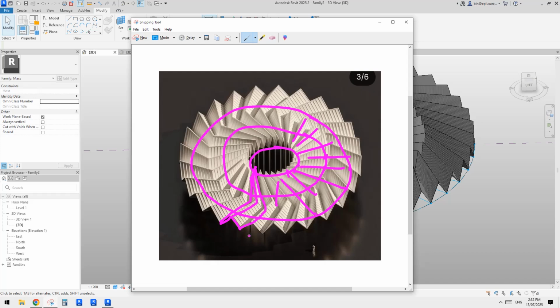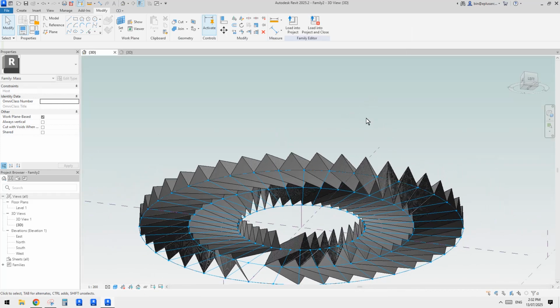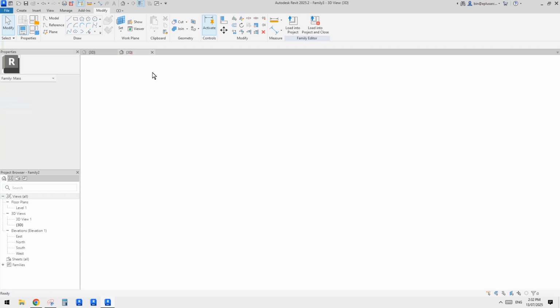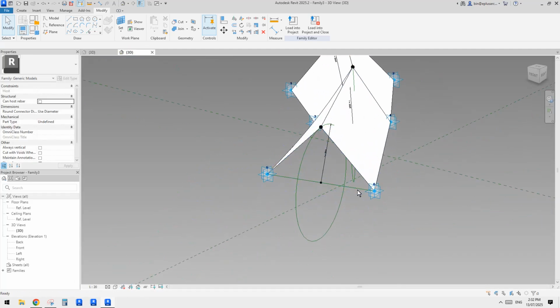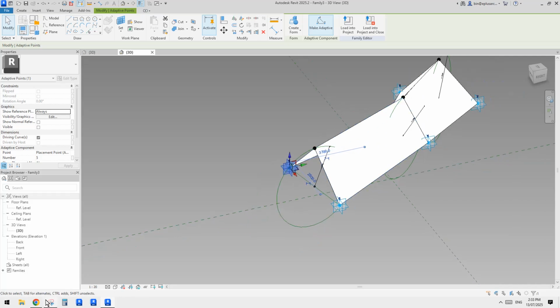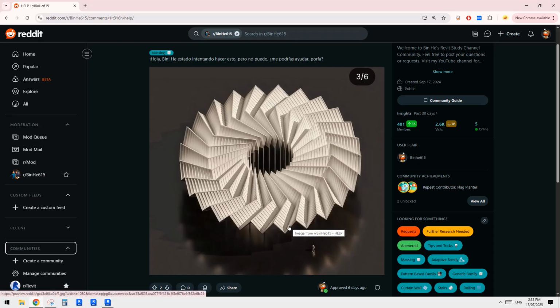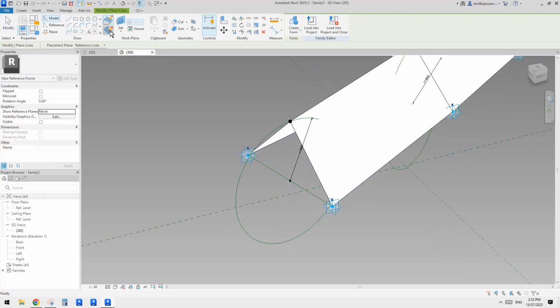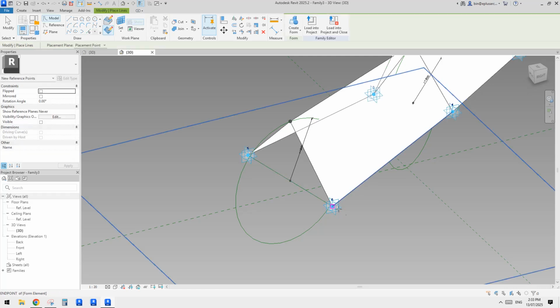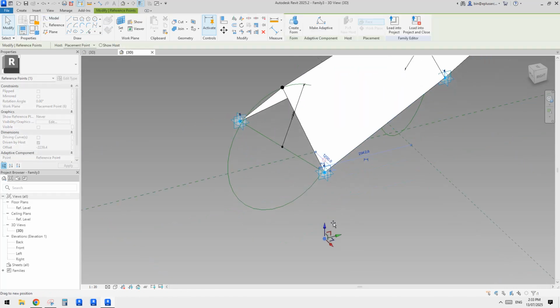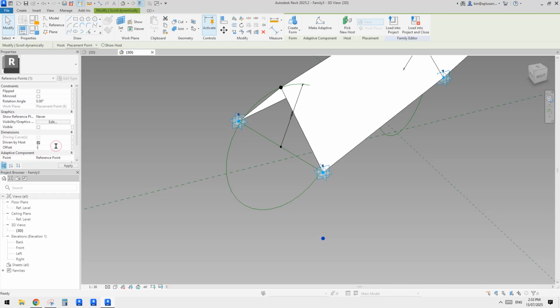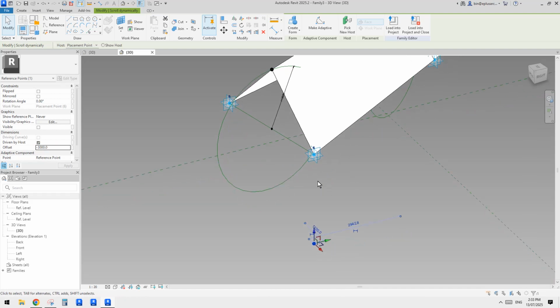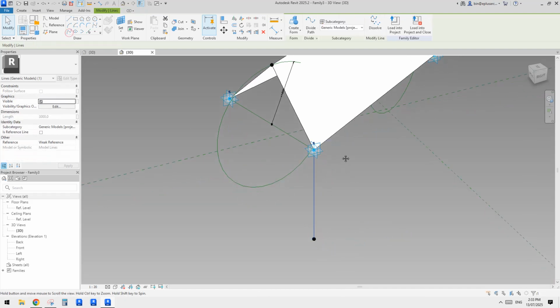Let's have a look again. Looks like we have some columns there. Yeah, I guess we can probably just go back here, like from each point. So currently we have this. We can probably just place a point, use draw on work plane onto all these adaptive points, and then we can just offset those points down, like for example, negative 3 meter, for example, right? So I'll just do one. Okay, and then we can just create.